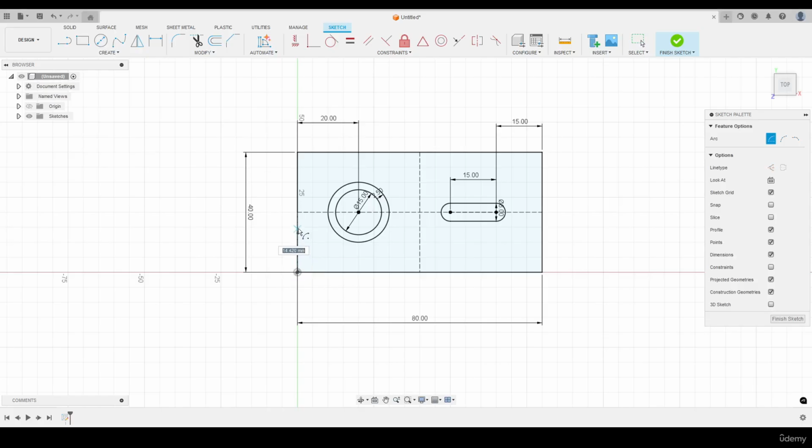I know the first point is defined on this vertical line at a distance of the radius, which is 12.5 mil. Okay, then click once, make sure we're snapping onto that vertical line, draw the arc around, and then snap onto the horizontal line here. Our arc in place. Now we can put this square geometry with a chamfer in here.